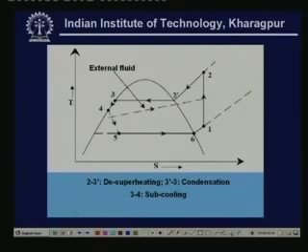And in this picture you can also see the temperature profile of the external fluid. Here the external fluid flows in the opposite direction, that means it is a counter flow type of condenser. As the external fluid flows through the condenser, its temperature increases because it takes the heat from the condensing refrigerant. In most refrigerant systems, the external fluid does not undergo any phase change.